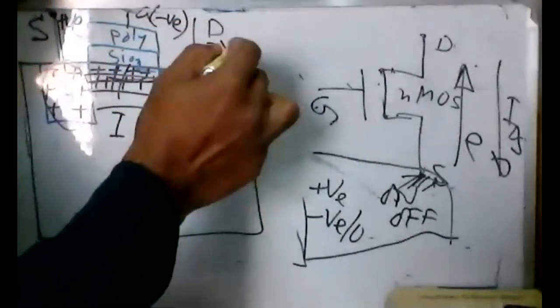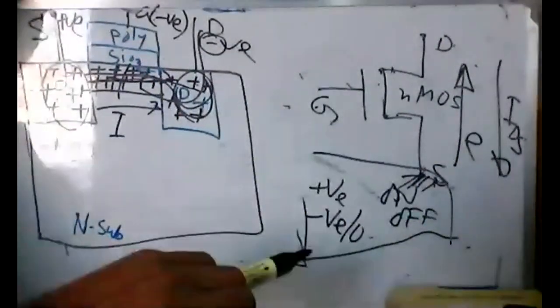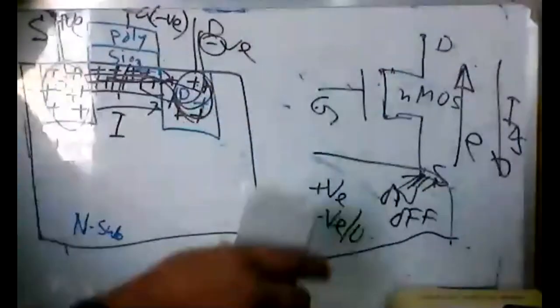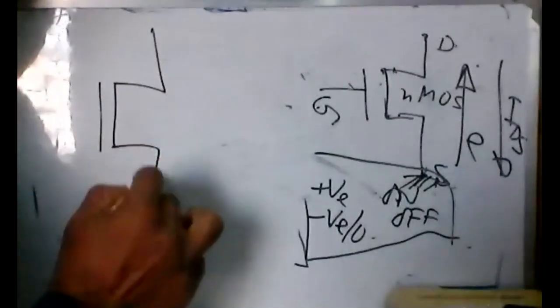So now if you look at that, in this case the source voltage is positive and the drain voltage will be negative, right? Because these holes will be here, and then they will be attracted by the negative and will go there. So this is the opposite direction of NMOS, and now if we make a symbol for that, we'll be done. From now we can design our circuit. The symbol is very similar, a little bit opposite.